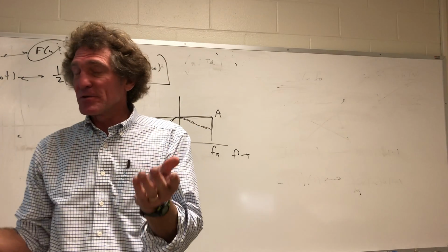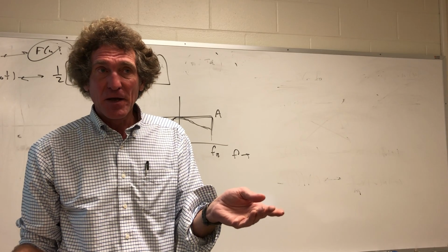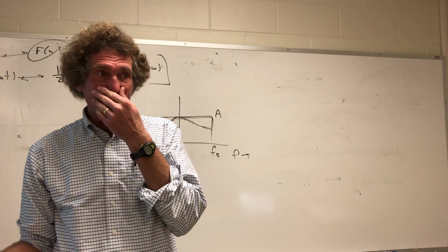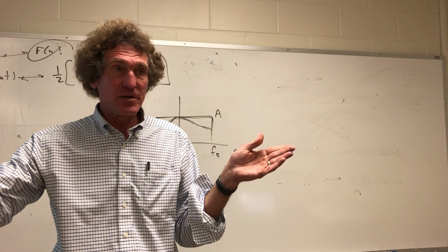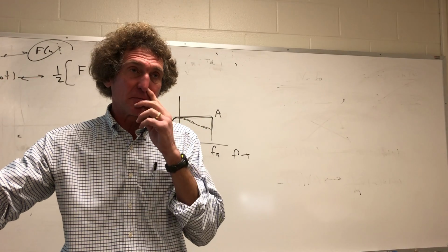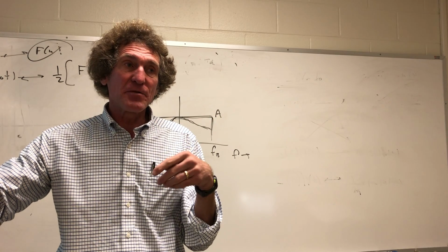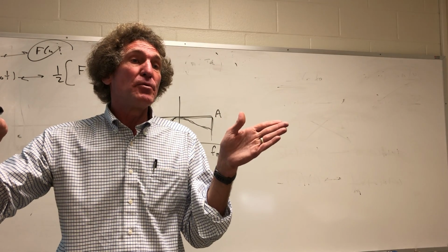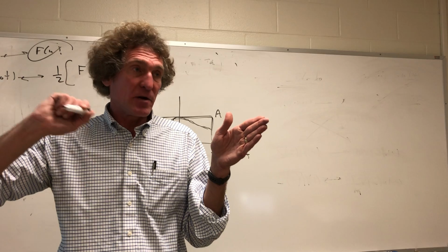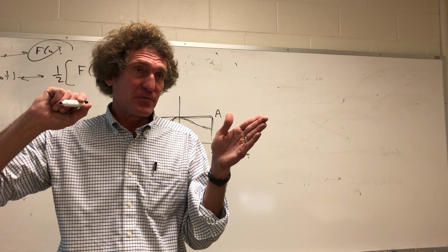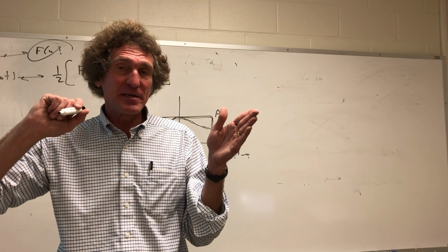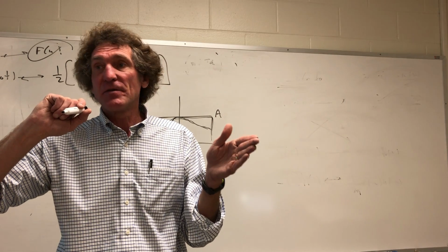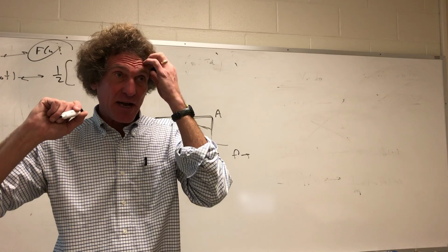This is what Bose did with his speakers. Professor Bose at MIT got fed up with lousy speakers, so he took lousy ones, got their frequency characteristics, the power versus frequency response, and he just built the filter so that now, no matter when he puts in 1 watt at any frequency, he gets 1 watt out of those speakers. And that was the Bose 901 back in about 1979 or so, 1978. And then I don't even know what they have anymore, but that was an active crossover.